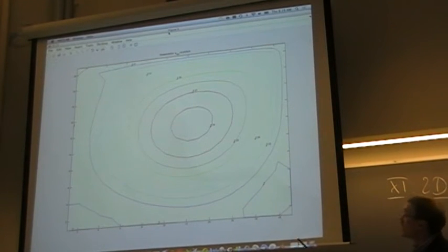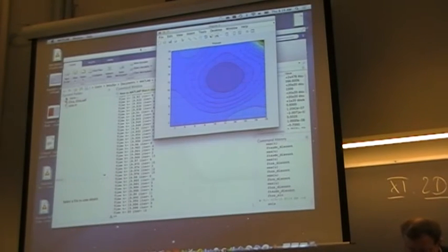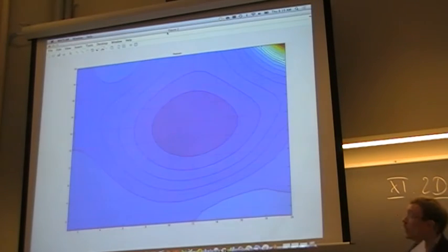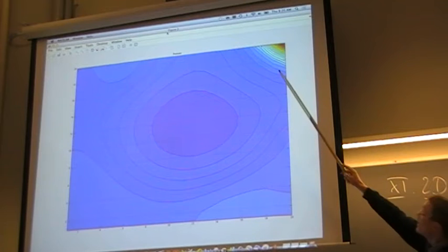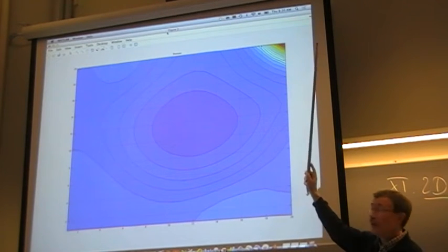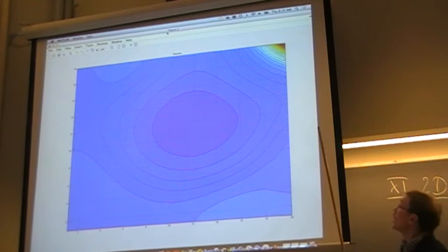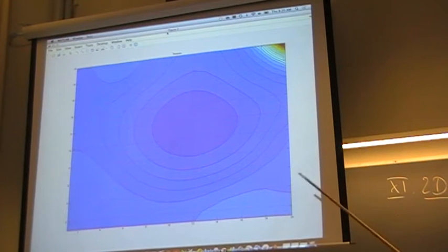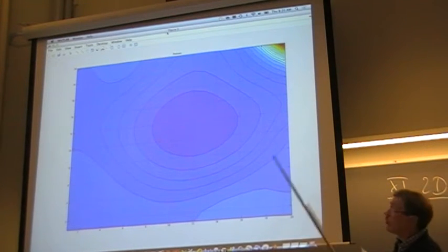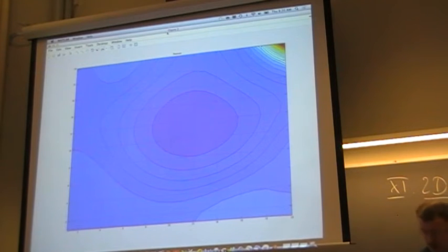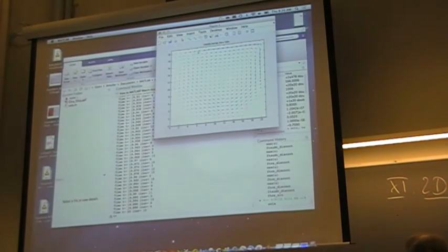So you see here the indication of that in the streamlines. And another result is the pressure, which is not so exciting, except for this singular point where the velocity is here non-dimensional 1, and here it is 0. But nonetheless, that's no problem. But we have a pressure spike here, large pressure. And else we have the streamlines.